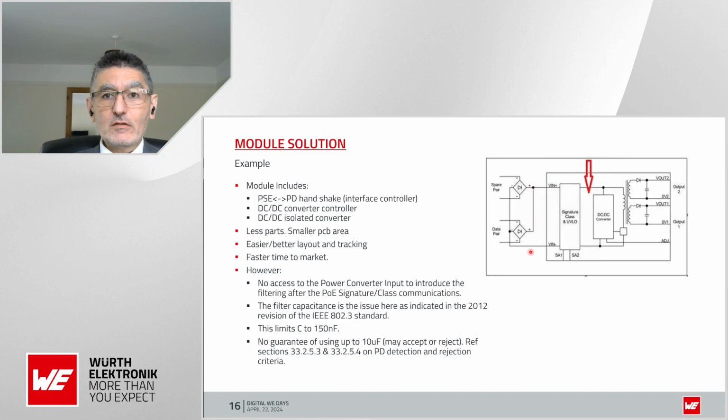The reason is that the IEEE standard limits the amount of capacitance and inductance that you can put on that interface, because it does impact the signature detection, the classification, I should say, of the PD. So as per the IEEE standard, and I mentioned clauses here out of the standard, you are limited in the amount of filtering that you can introduce, which can be an issue and a problematic one for that matter.